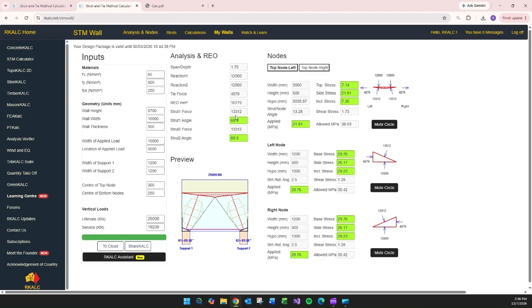Maybe if you wanna, so you look at the reinforcement here is 10,000. That is a lot of reinforcement essentially for this given load. Maybe your aim is to reduce that reinforcement. So how will you do that? It will be essentially increasing the depth of the wall, or playing with the loading. Maybe you want to reduce the live loads because the building has typical height. So looking at this one, everything is working fine.